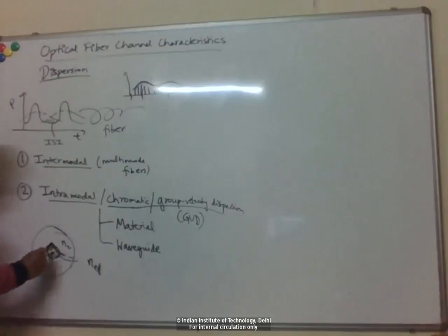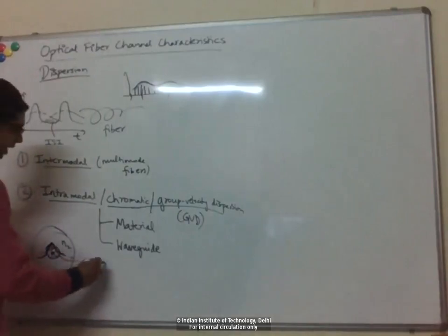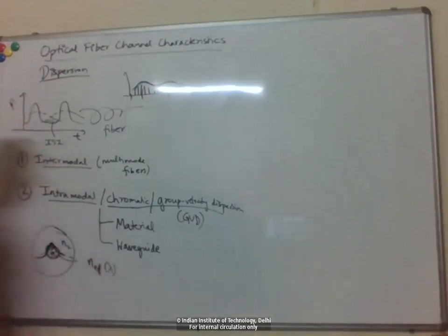Right? So this confinement factor, of how much power is in the core and how much is in the cladding, changes slightly. Or in other words, this n effective is a function of wavelength, even if n1 and n2 are taken as constants, not a function of wavelength. Right? So this is just an effect of the waveguiding, that the mode profile is changing with wavelength, even though the material refractive index is taken to be constant, right?